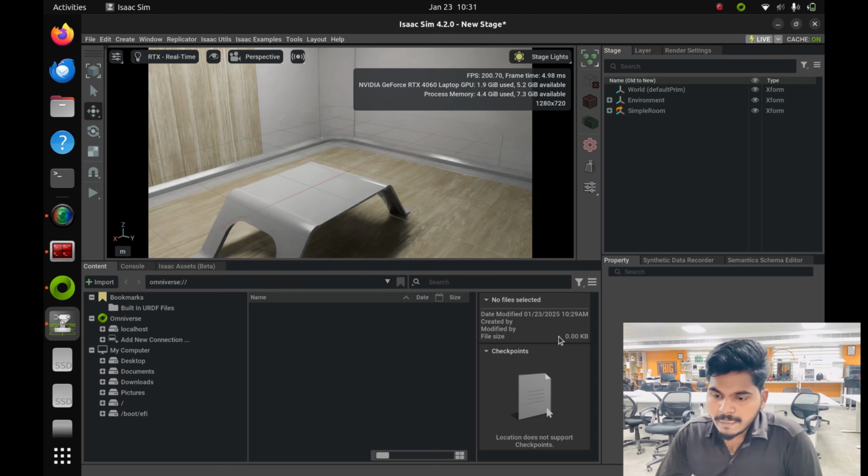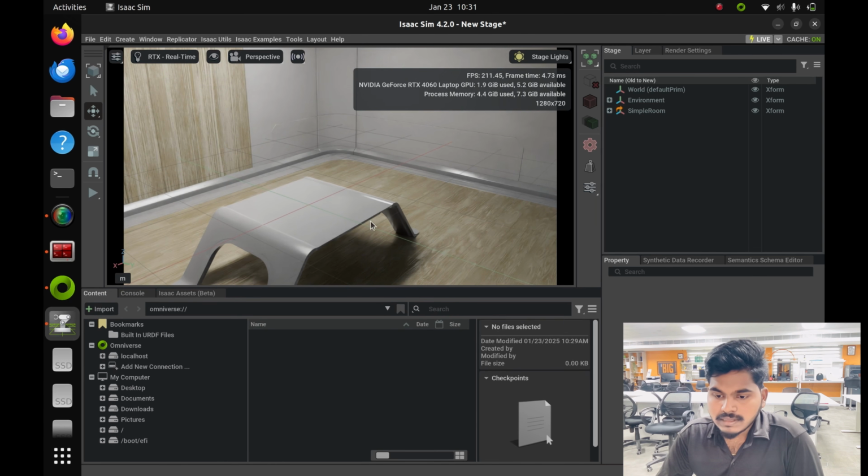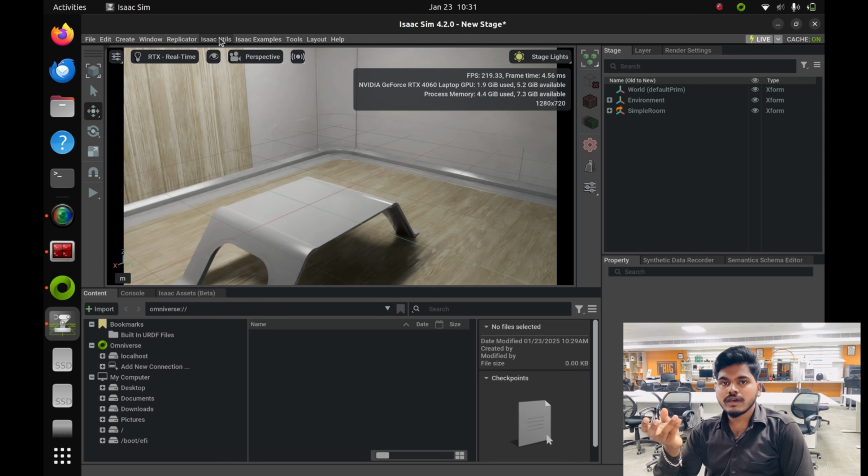For the scan topic, here we've been using a lidar in the simulation environment. In an empty environment I'm gonna import my robot. Basically in ROS1 or ROS2, how do we import any robot? Normally we would design a robot in Fusion 360 or SolidWorks, then convert that model into a URDF using URDF exporter plugins. Here it's the same thing, but I'm gonna use the TurtleBot 3's URDF.